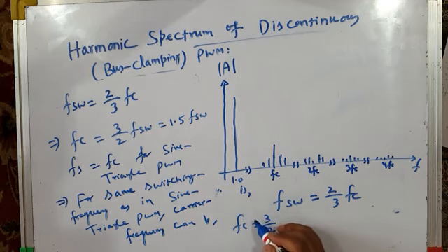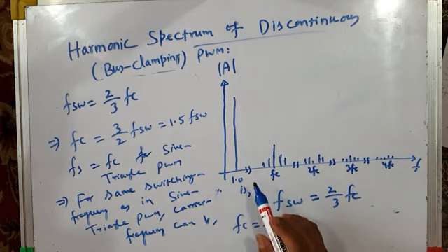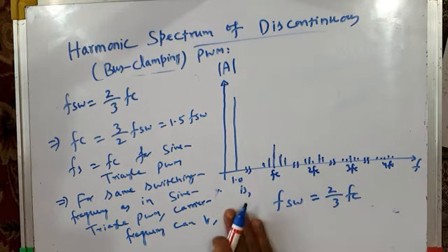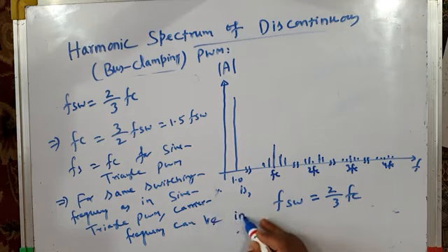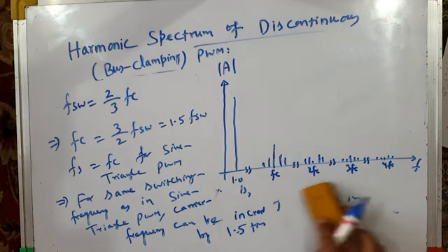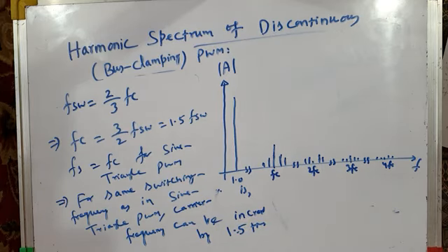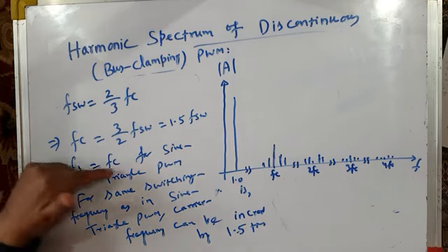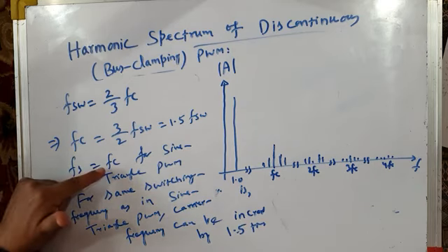I can increase carrier frequency. My carrier frequency can be increased by 1.5 times. Try to understand this point. It's very important. For sine triangle PWM, switching frequency is same as carrier frequency.